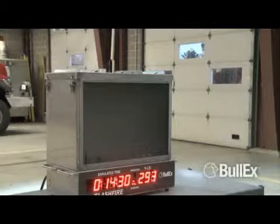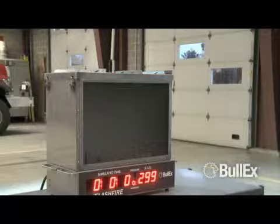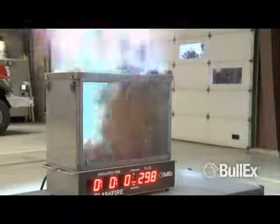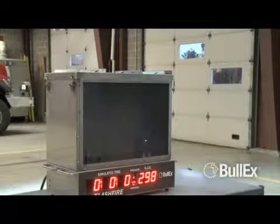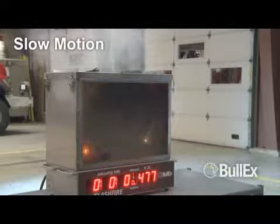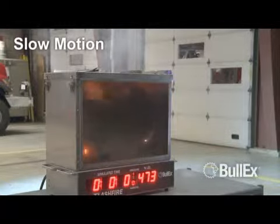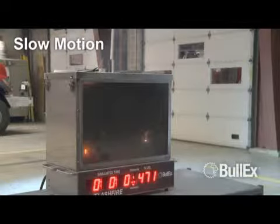An ideal gas explosion demonstrates a scenario where the gas concentration builds past 100% of LEL and an ignition source is then introduced, triggering a high-energy explosion. Oversaturated conditions can also be created to show the effects of improperly ventilating a structure with a gas concentration above the upper explosive limit with an ignition source present.